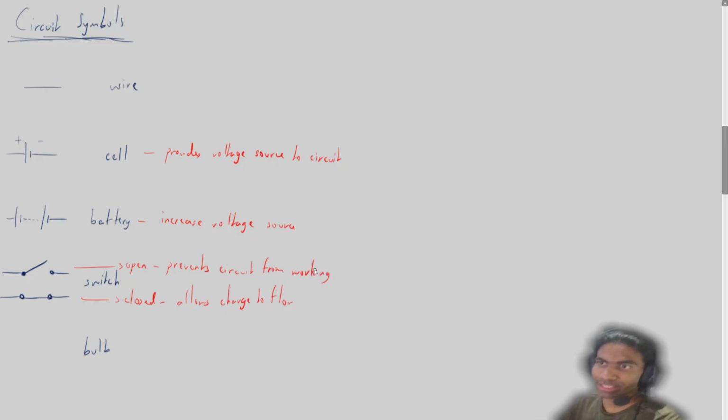Okay. With that said, just because the switch is open, or the circuit is switched off, doesn't necessarily mean that it's safe to prod around in there. The most dangerous thing in the circuit is the EMF source. So even if a switch is on, you still have to make sure that the EMF source is disconnected from the circuit. If there's a wire from the EMF source that's still something that you could touch, and a part of your body is attached towards a lower potential like the earth, then that could cause electrocution.